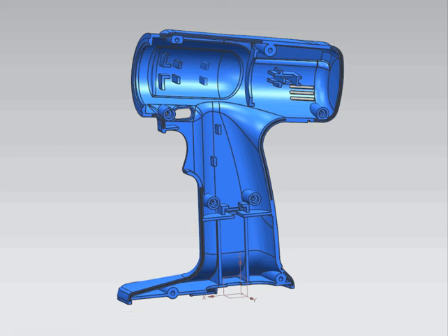This example shows how you can use synchronous modeling commands to rapidly create concept parts when speed is more important than a highly engineered chain of associativity. Use these techniques when the part does not contain a feature history, or where the features do not provide the design intent you need to make your changes.